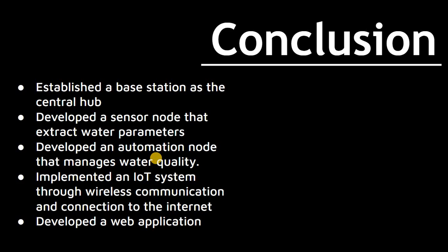The main goal of the study, developing a monitoring and management system for aquaculture purposes, was met. Problems brought about by conventional methods of water monitoring and management were addressed through the integration of an IoT system where digital instruments were implemented. Water monitoring and management devices were automated and can be controlled wirelessly and remotely through the development of a web application. Data gathered from the digital sensor node is proven to be within an accepted error range, with the USC Water Laboratory readings used as reference. Human error in maintaining a fully controlled environment accounted for virtually all of the errors the system had experienced.